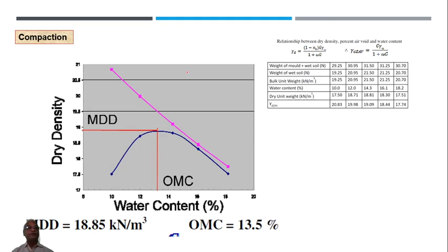Okay, here they have plotted the curve. Simultaneously you have got a compaction curve also, so with a water content of 10% here, the dry density achieved is 17.5, whereas gamma D ZAV is 20 point something, 20.83, there it is. So with 12% the actual is here, the imaginary ZAV line is there. So likewise when you go on drawing it, this is what the ZAV line, or gamma D with zero air voids, will look like.